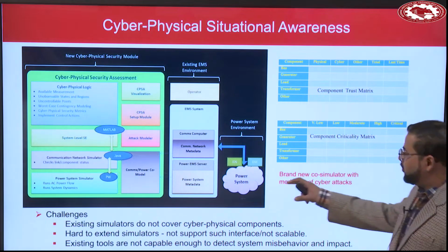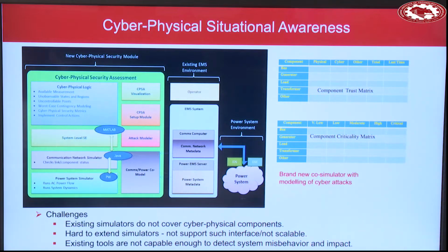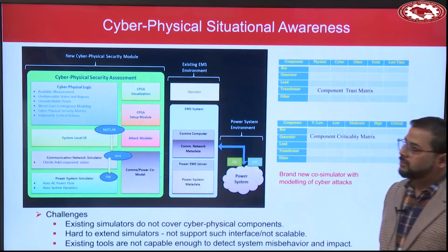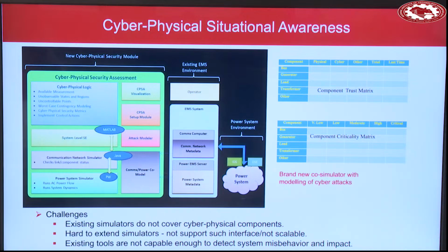Okay. So within the power system, let's say at each substation we have something called a state estimator. We can call it a distributed state estimator. So when you are injecting data, collecting data, and sending it to the SCADA, before collecting, we have some algorithm in place that can look into whether the data we collect looks okay or not. If not, sometimes data could be corrected by the algorithm, right? But generally, they are at the local level.